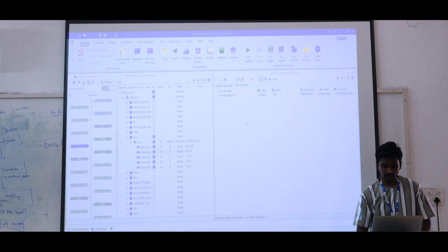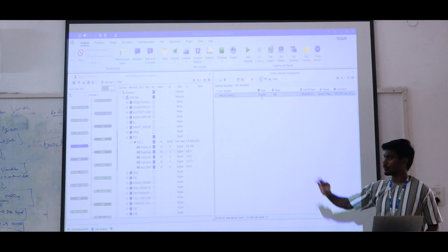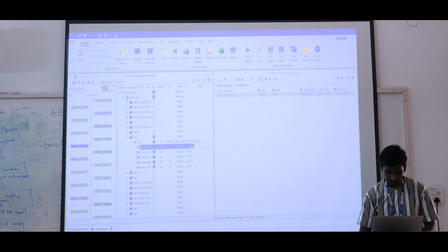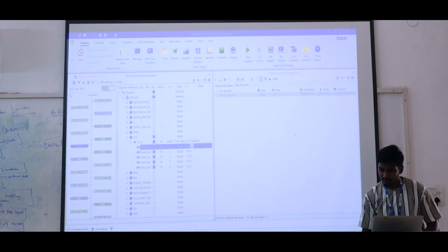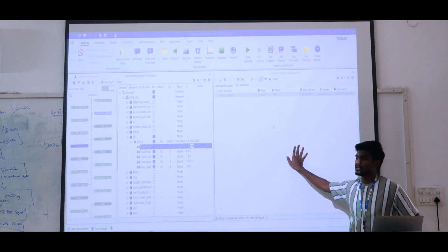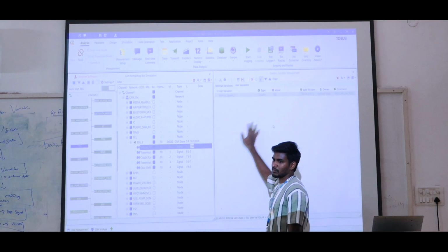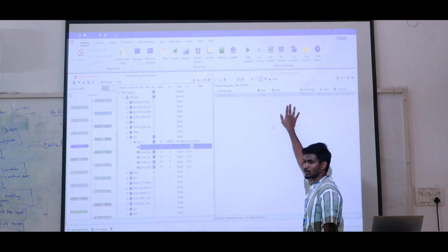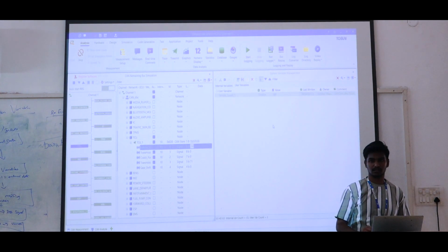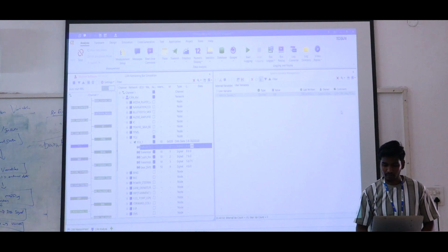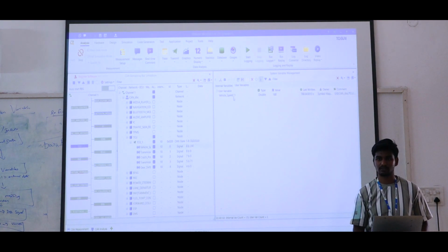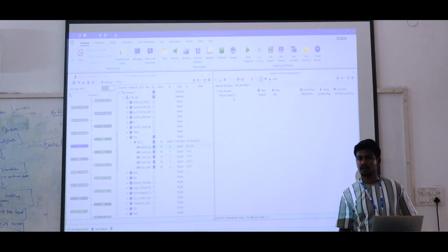In bidirectional, for example, now this variable value only gives the values to the RBS signal. For example, here you can set a value, that means you will not get it from user variable. So the bidirectional values, if you are setting means you can change from here also, it will be reflected here, or also you can change from here also, it will be reflected from RBS. So that is called as a bidirectional. Okay. So before going to bidirectional, this feature also carries some IG block properties. So I will explain that after we move to bidirectional.